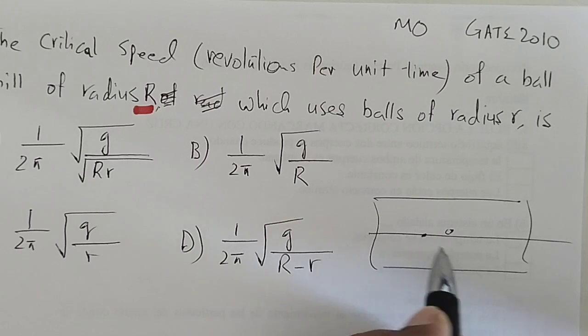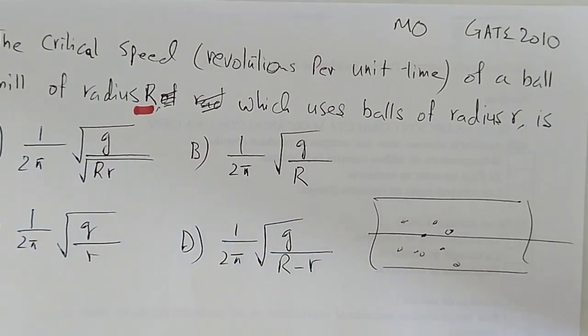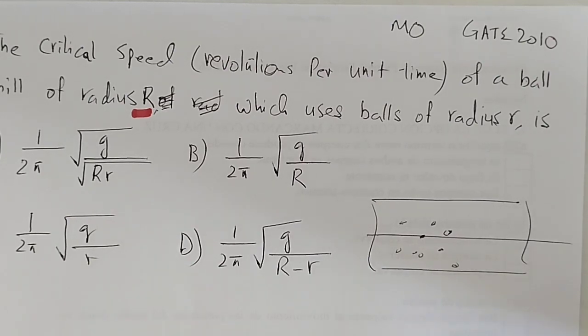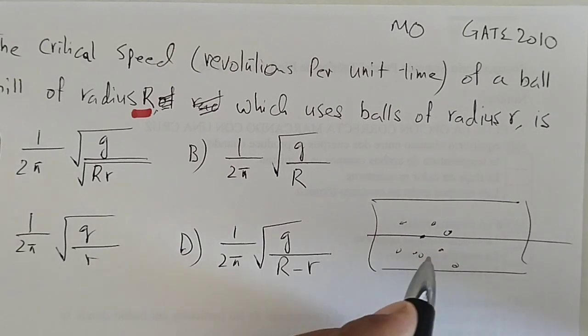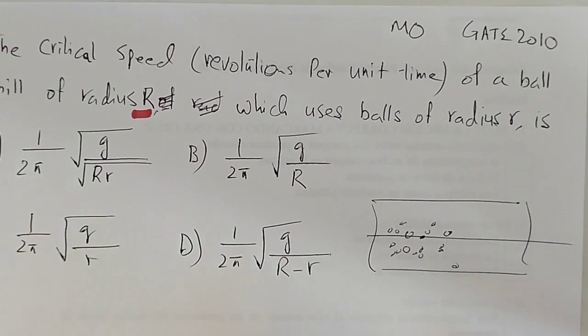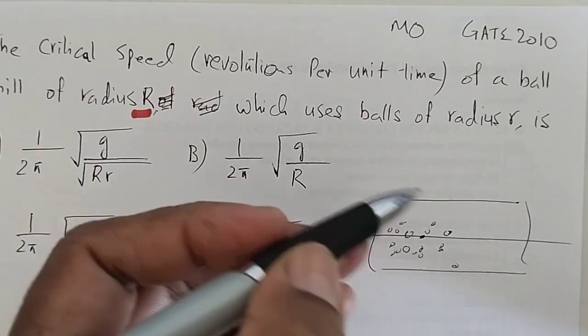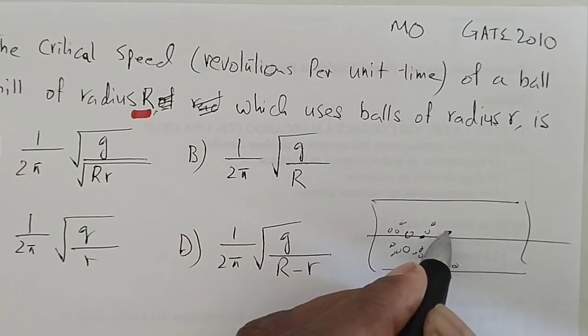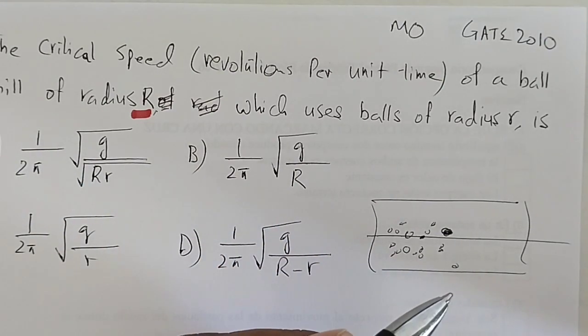This ball mill is used to reduce the size of the particle, or to make the particle more granular in nature, grinding. So it uses different sizes of steel balls of around 1 to 5 inches, and when this mill is rotated, there are 2 forces acting on the particle. One is centrifugal force and another is gravity force.